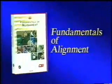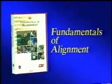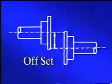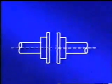In another program on the process of alignment, we pointed out that there are two types of shaft misalignment. One is angular misalignment, and the other is offset misalignment. In angular misalignment, as the shafts rotate, the coupling firmly holds the ends, causing them to bump once in the radial direction as they attempt to correct themselves. The rotation forces the shafts to push away from each other in the axial direction.